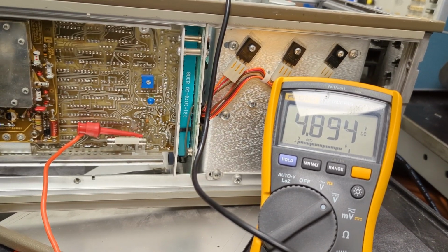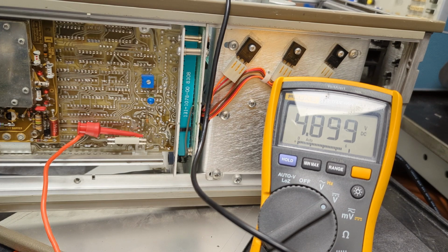Okay, so I had already done some tracing of the voltages from the mainframe, which is outputting 8.2 volts. On the 500 it would be 11.5, and I traced that circuit using the schematic. Obviously the voltages are going to be different, but the voltage drops seem to match up until I got here. So this is the first discrepancy, and this is a bit odd.